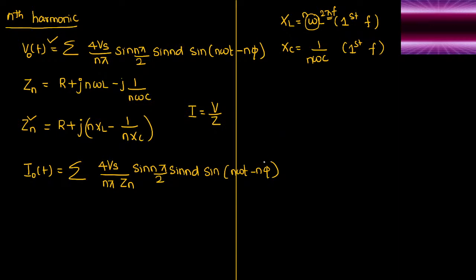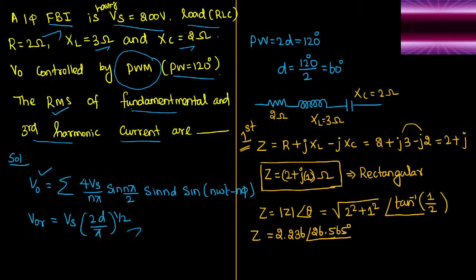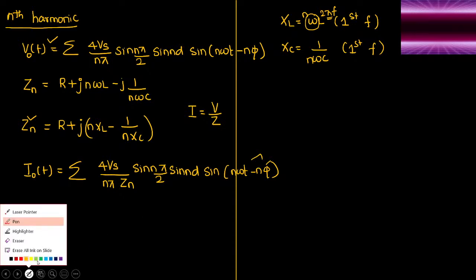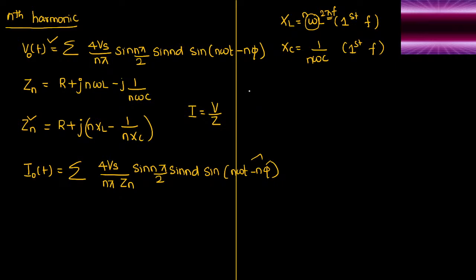For our question, this pi has been calculated for the fundamental. We have what we saw, that is the impedance angle 26.565 degree. That is only for the fundamental. Anyway, this is the generalized expression for the current. We did the next one successfully also. So our next one.